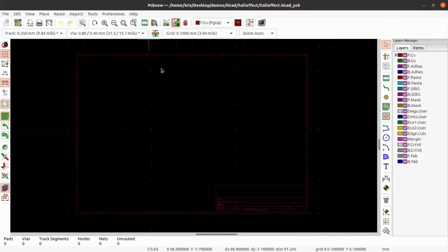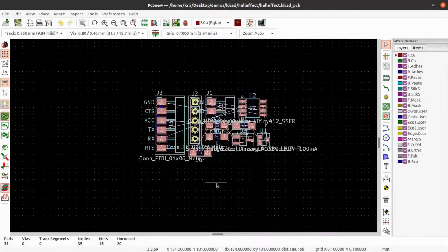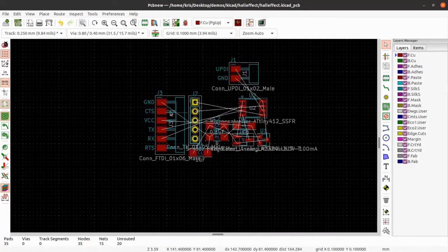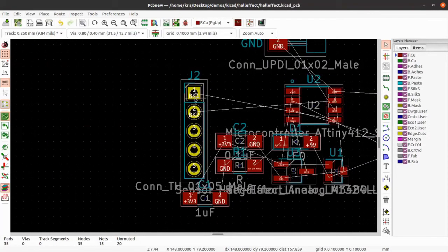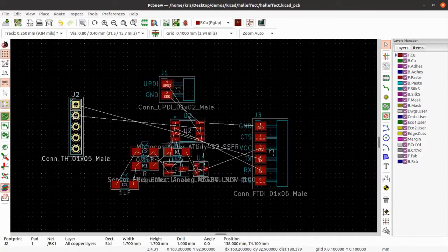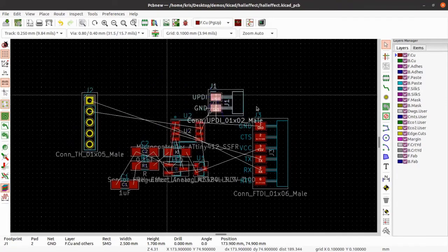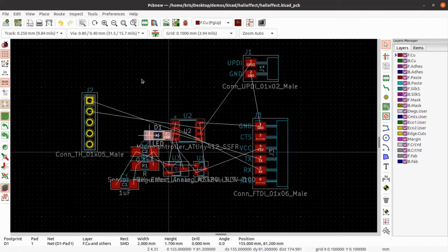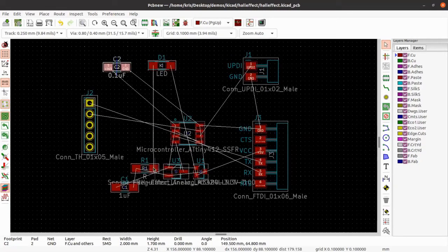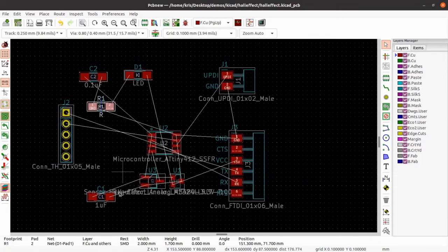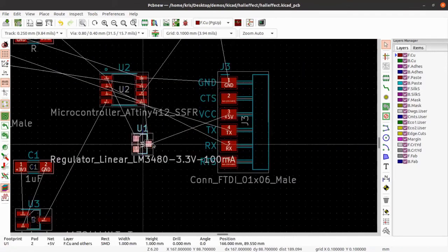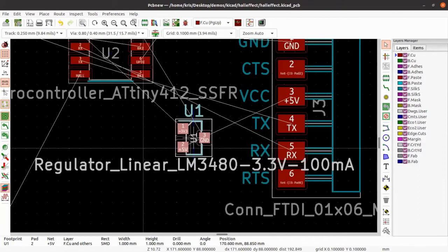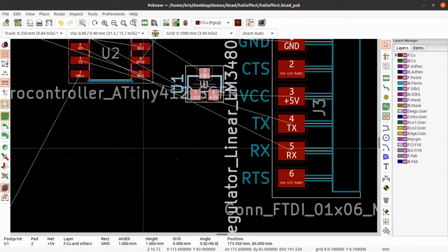Over here, insert the netlist, and start laying it out. One thing that I wanted to introduce in this video, of course, was the through-hole headers, but it was also vias. For some sensors, it's going to be quite hard to route the connections around the components. So I'm going to move this a little bit further just to show how to solve that by using vias, moving your PCB manufacturing skills to the level where you can actually deal with double-sided boards.